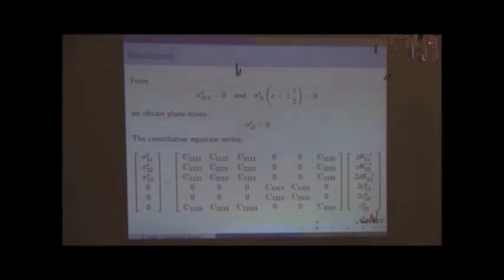You can write the constitutive equation. I've put here what we know about the in-plane strain, which is linearly distributed. I detailed all the components, and those are unknown. You can readily see that the transverse shear strains are zero because of the uncoupling. The last thing to be determined is the normal strain, and the normal strain is determined by this line.